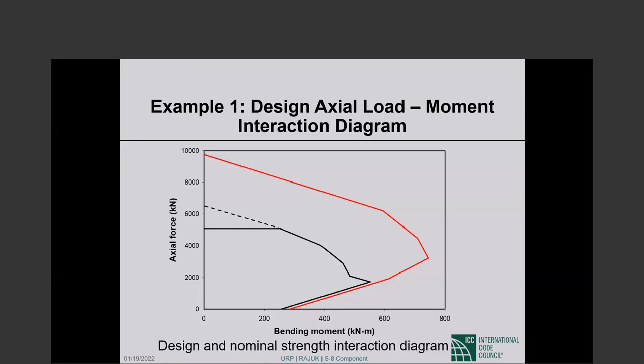Now let me continue a little bit. Let us say in that 12-inch by 12-inch column, instead of 4 bars, you had 6 bars. So there are 2 additional bars, and somehow you place the additional bar not in the middle. If it were in the middle, you wouldn't go beyond the 6-inch clear spacing.